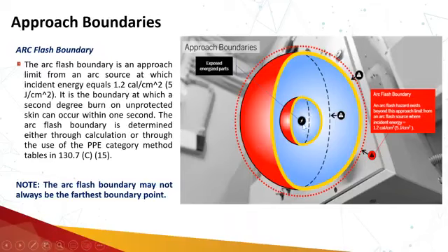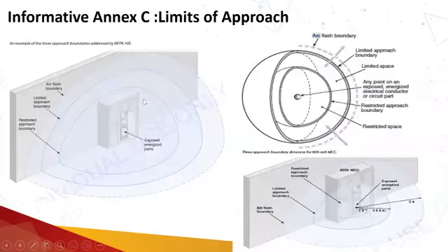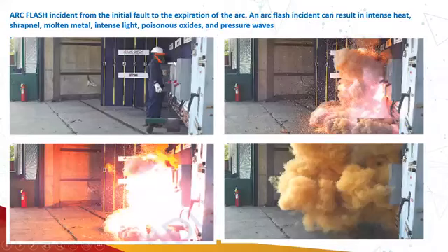So at this point, my equipment is there. In case any arc flash event occurs, the incident energy will be high because at that particular location, a high amount of incident energy will be released. As I move from the center, or the point from where the arc flash initiated, it will decrease over the period of time.